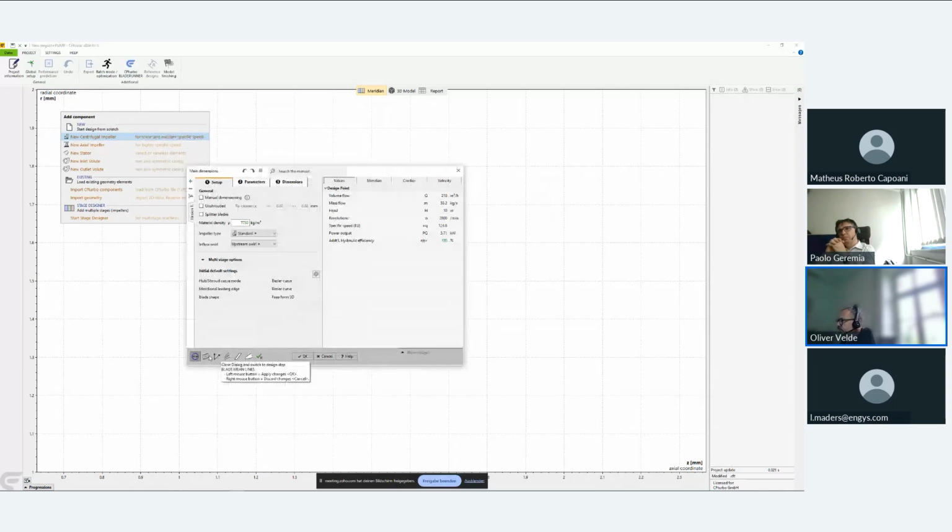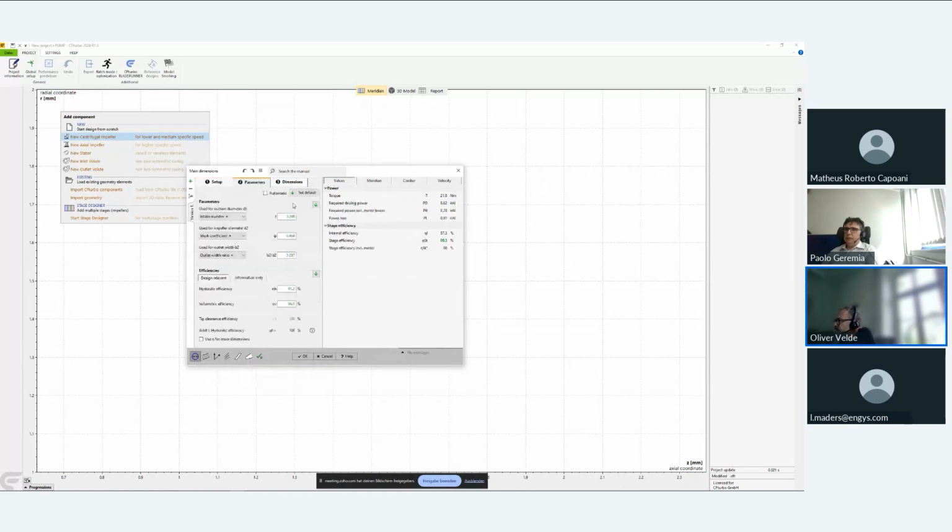Every design step defines a unique design parameter, which means if you want to change that later on, you can only do that at one particular location in the process, and that's a precondition for being able to incorporate CFturbo in, for instance, a batch run, into a DOE or an automatic optimization. Okay, so what I have to do is go through those 6 design steps before the design is finished. As I said before, we use the solution of balance equations as well as empirical knowledge.